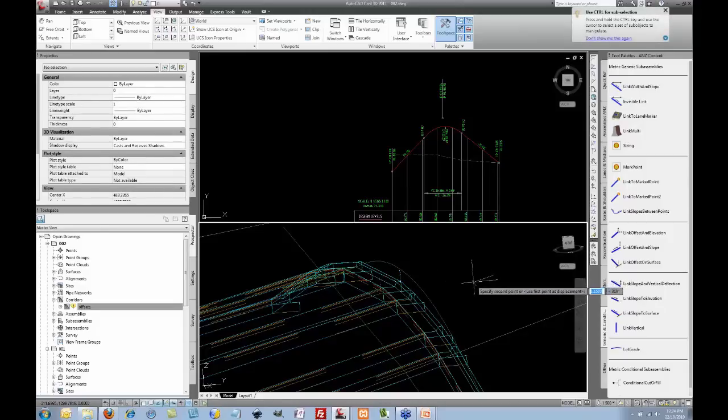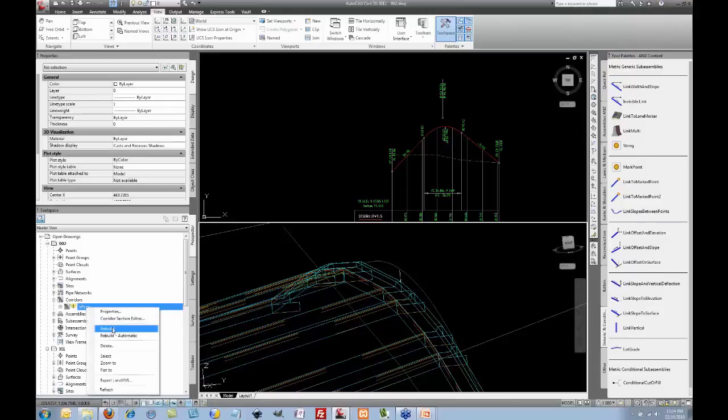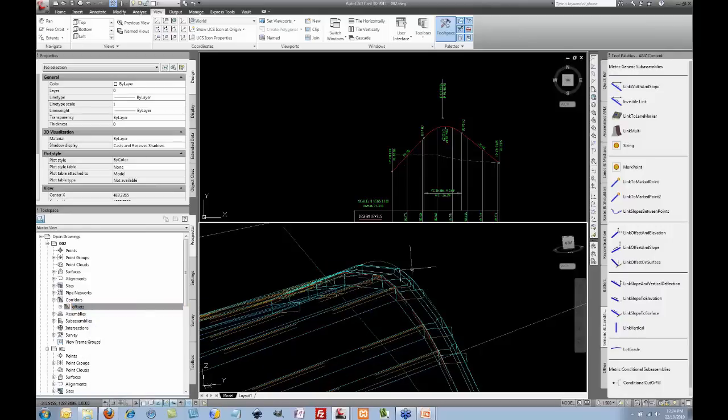Normally what we would do is raise this line here and project outwards. We're working from the outwards inwards, but that's the real point we're making here. So now when I right-click the corridors and rebuild, it first of all drapes the curb on, and then the footpath, then the lane travels from the curb back towards the center line.